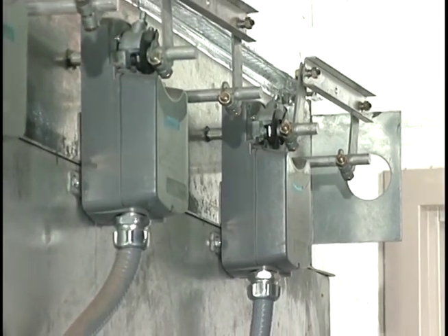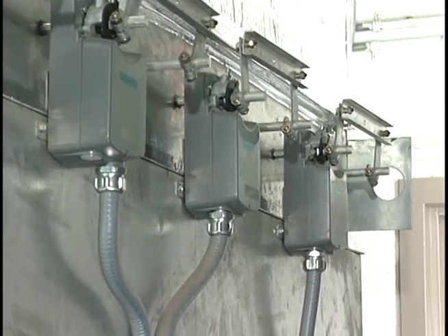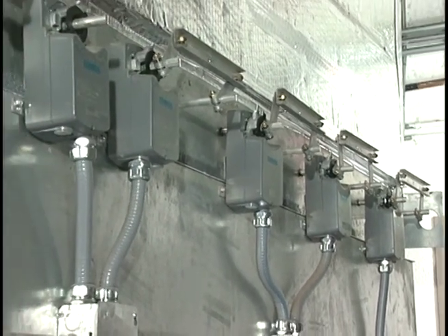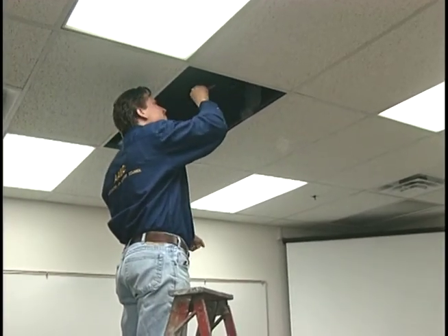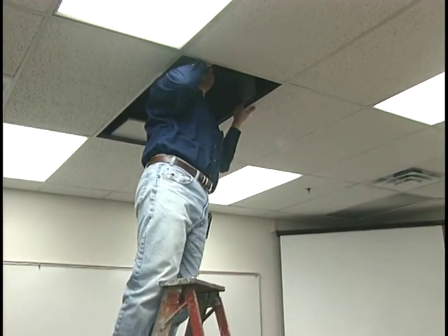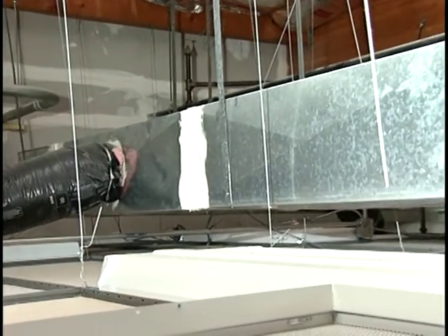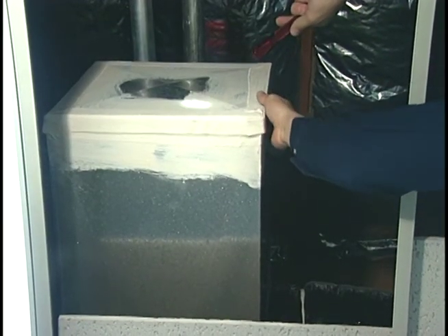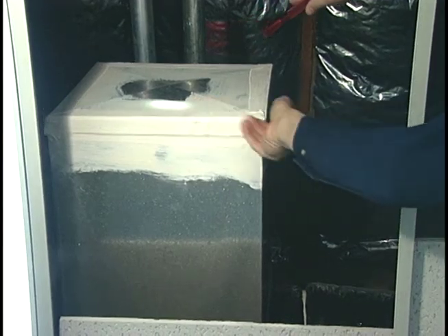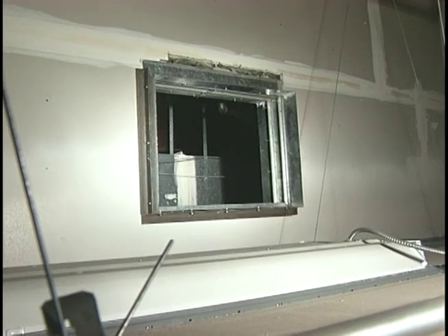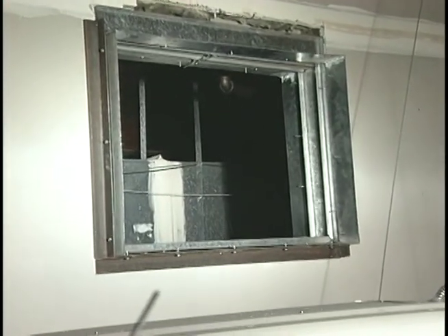The controls, including automatic control dampers and fan volume controls, are also inspected to determine if they are complete and operational. The supply and return air distribution systems are inspected to determine if the ductwork is intact and installed according to the drawings and specifications. The ductwork must be free of debris with no inappropriate openings, such as end caps left off. The ductwork is also inspected to determine that there is an unobstructed path from the fan to each conditioned space and back to the fan.